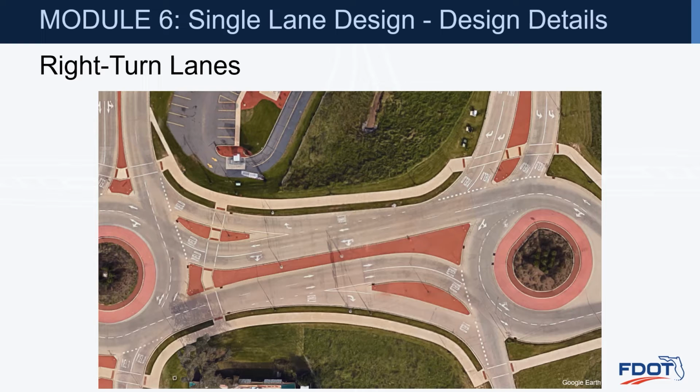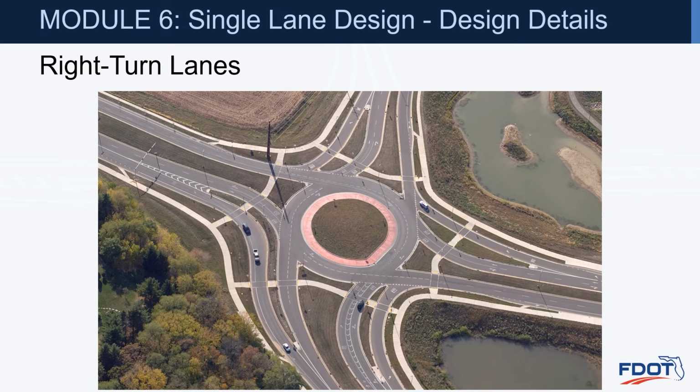Here is another picture showing in this case right turn bypass lane. So you can see a partial right turn at this location as well as a partial right turn there. So those are single lane partial right turn bypass lanes. And actually on the top here, you can see that this is a dual partial right turn bypass lane. This picture shows a free flow right turn bypass lane as well as partial right turn bypass lanes on this leg as well as the other two legs.